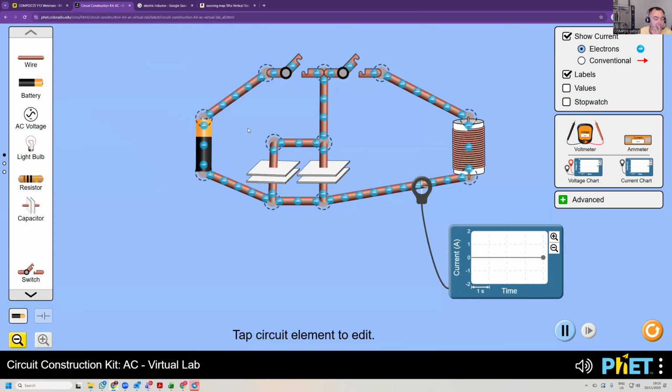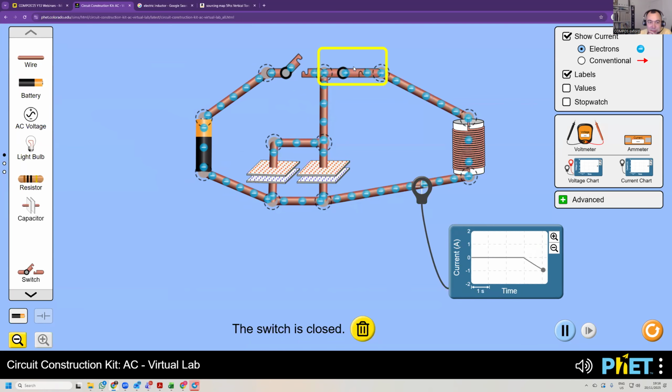Okay, so first we will charge the capacitors. So you can see I've charged the capacitors. Now the top is positively charged, the bottom is negatively charged. I've disconnected the battery. So now I'm going to discharge the capacitors through an induction coil. And you can see that the current reverses. The current goes back and forth, back and forth. This is what we call an oscillating circuit.